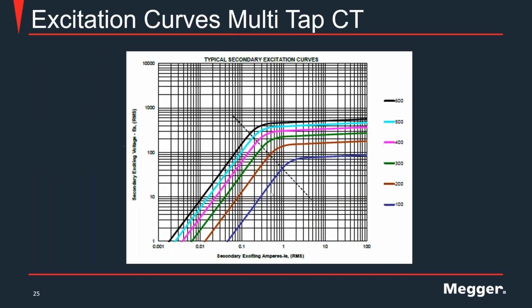So in order to revert that state, in order to misalign those dipoles, we need the same effect, but in opposite direction. We need a magnetic flux established in the core of the CT. So that cannot be achieved with just earth or grounding the CT itself. So again, we need the same scenario as that caused that magnetization, but again in opposite direction.